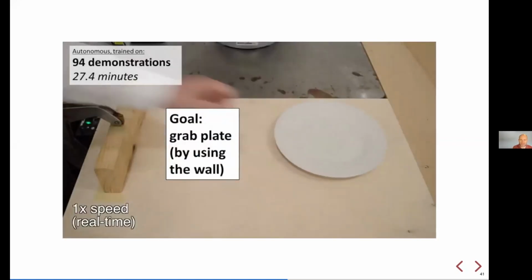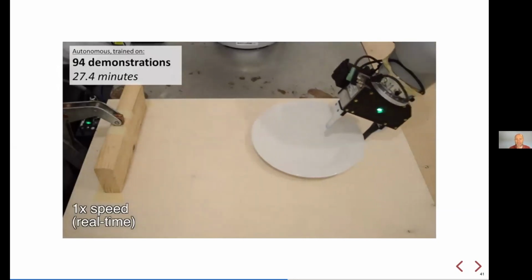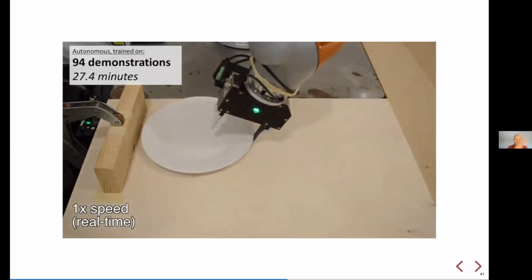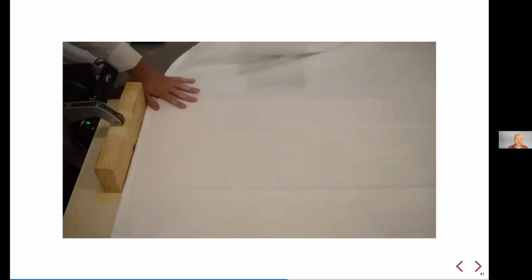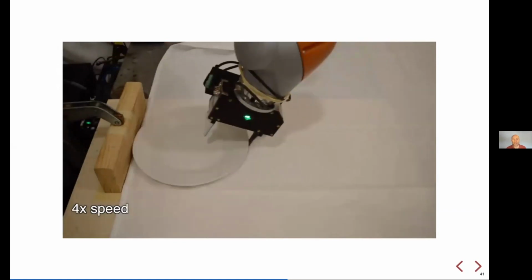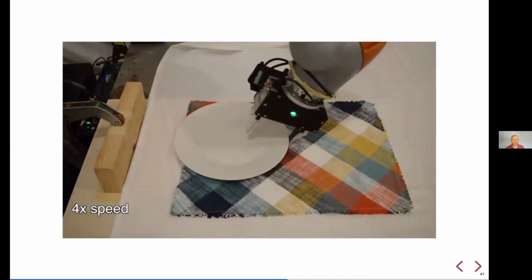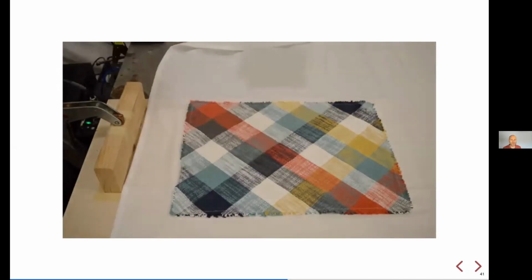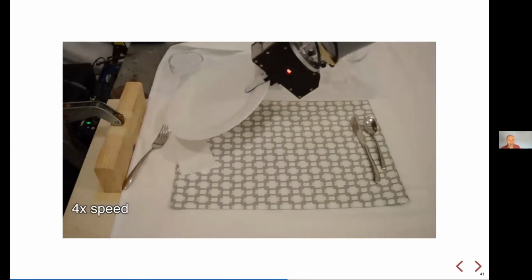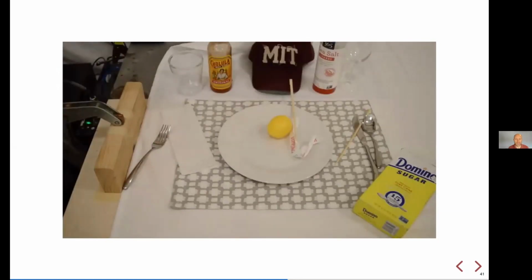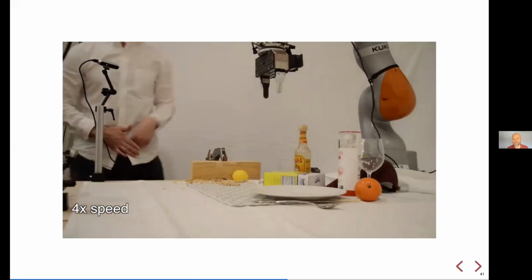Okay, so let's dig in on one of my favorite examples of that. This is just picking up a plate, but it's got some pushing in it. That's actually an unstable pushing. The plate wants to weather vane around and get behind you. So that's a non-trivial multi-contact task, and it's closing a feedback loop with the camera, right? Despite the RGB values changing a bunch, those dense descriptors give us a robust representation that can ignore the irrelevant details. The policy seems to do very well despite distractors and differences in the dynamics. This was the first time where I was like, you know what, we're starting to see robustness again.